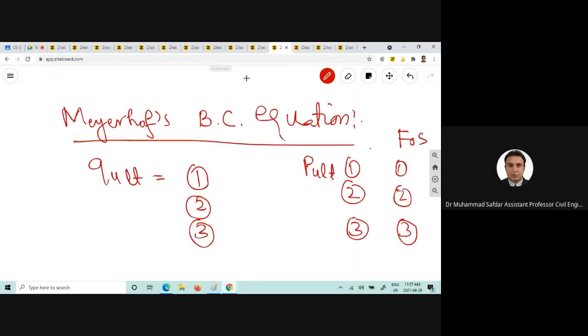I'm getting 7.21. Okay, 7.21. Let's go with the blackish one this time. 7.21. Okay, that would be in kilopascal. So we got the first ultimate bearing capacity of that soil. Using all those bearing capacity factors, shape factors, depth factors, and inclination factors, we came up with 7.21 kilopascal of the bearing capacity of that soil.